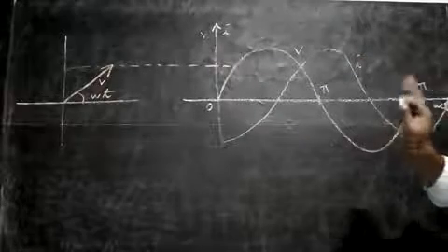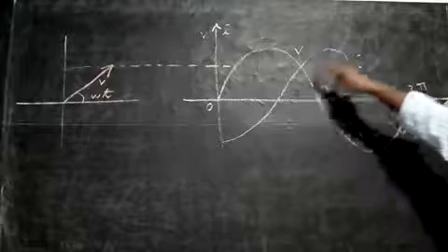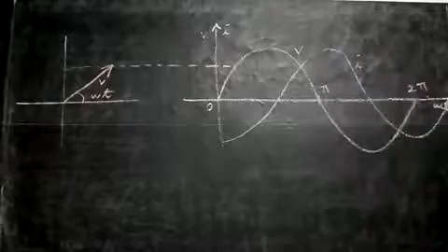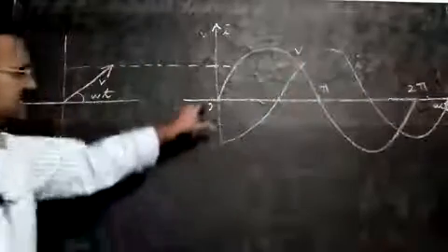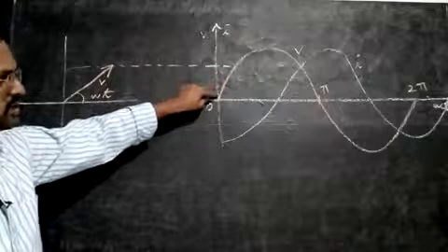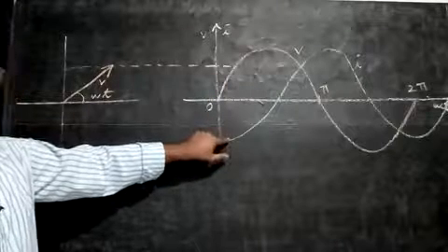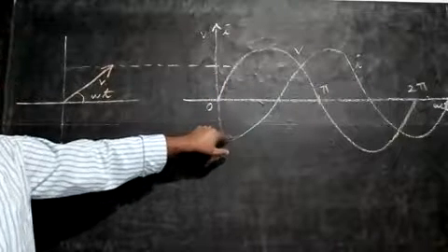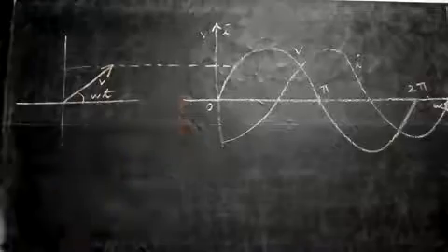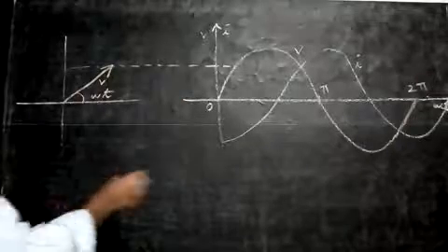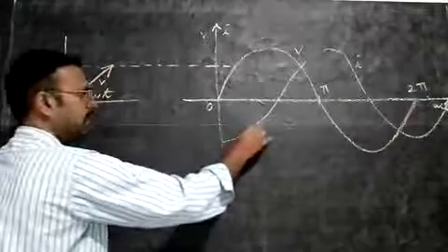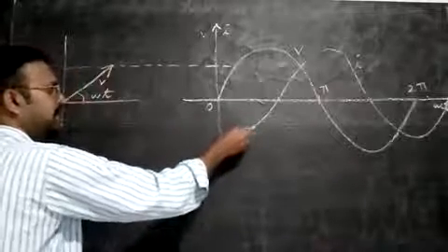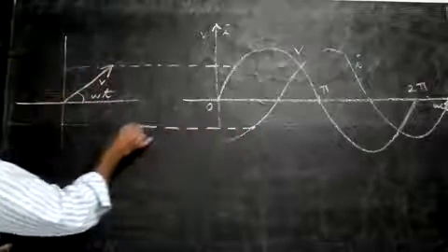Actually there are instruments called oscilloscopes. On that you can see the waveforms. Now you can see the current starts a little later only. Voltage starts first and the current starts a little behind it. This angle, you see, will be pi by 2. Let's see that now. For current we'll draw a vector here. So let me choose a point here. I'll see it later. So we'll put dotted lines here.